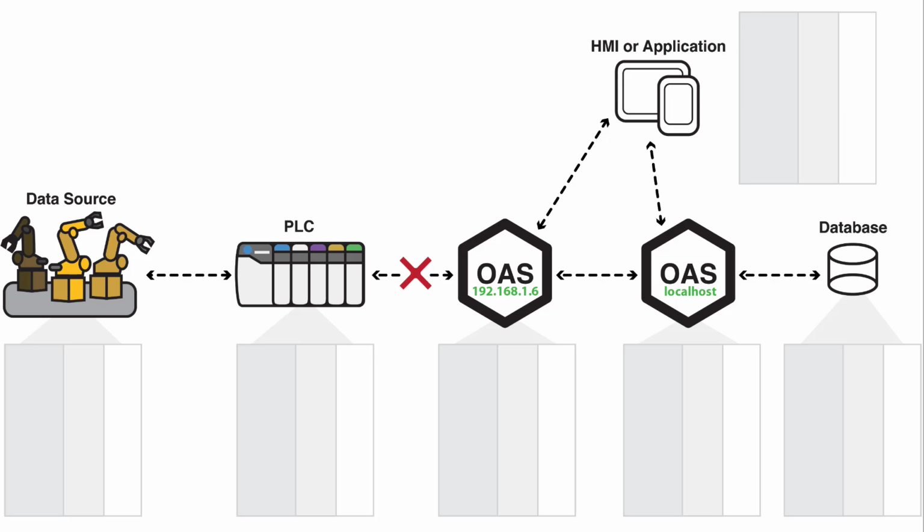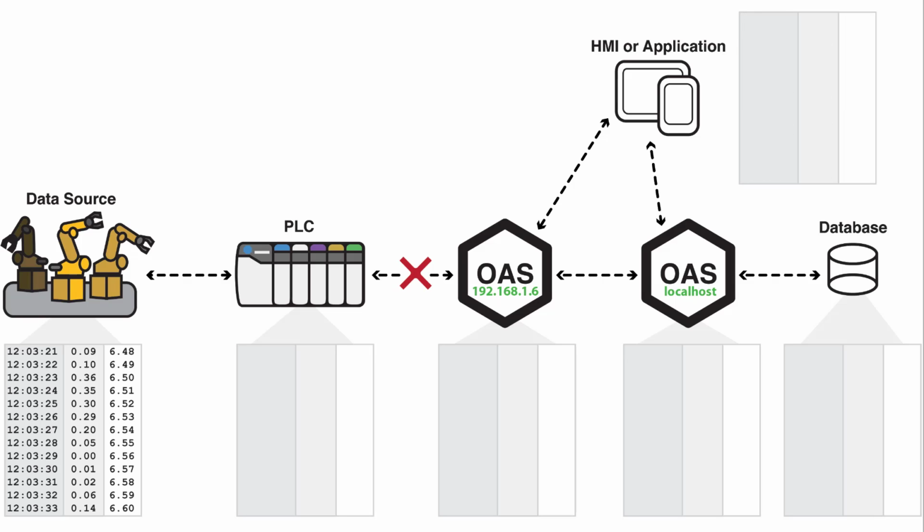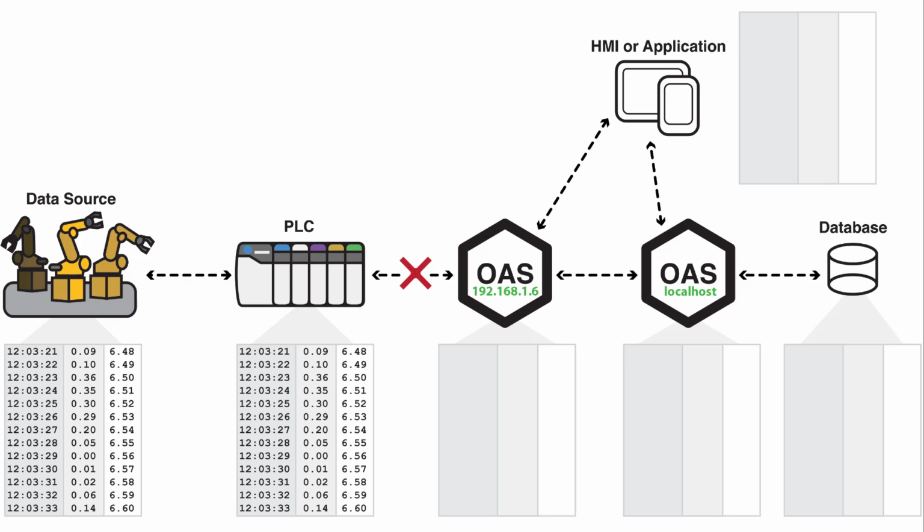So let's say in this scenario, while we're not able to talk to the controller, it's received the data from the data source. It now has it buffered, so that when the communications is reestablished to the controller, we would then be able to pick that back up. Or another way to handle that is you can have OES set up for failover mode to a secondary controller.